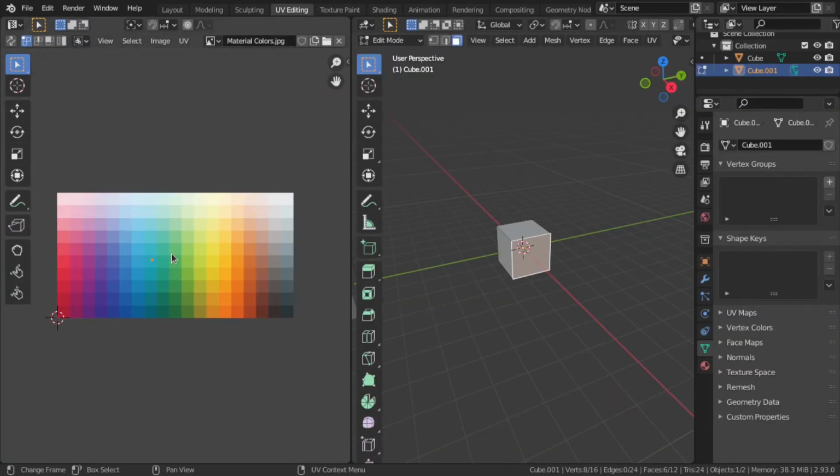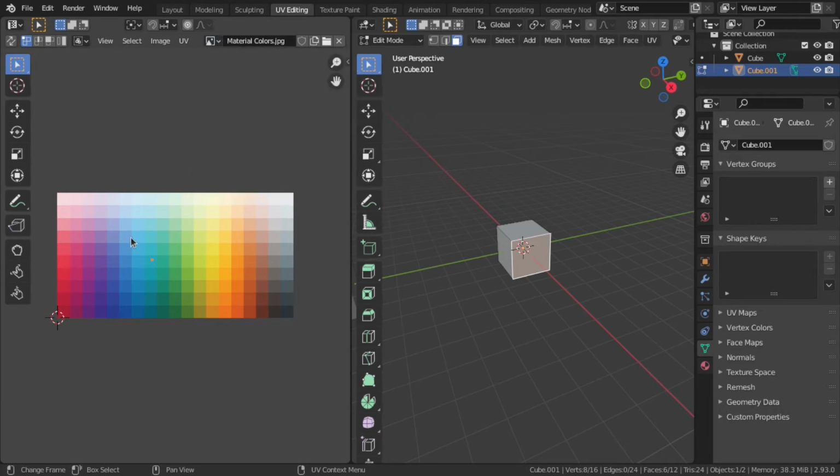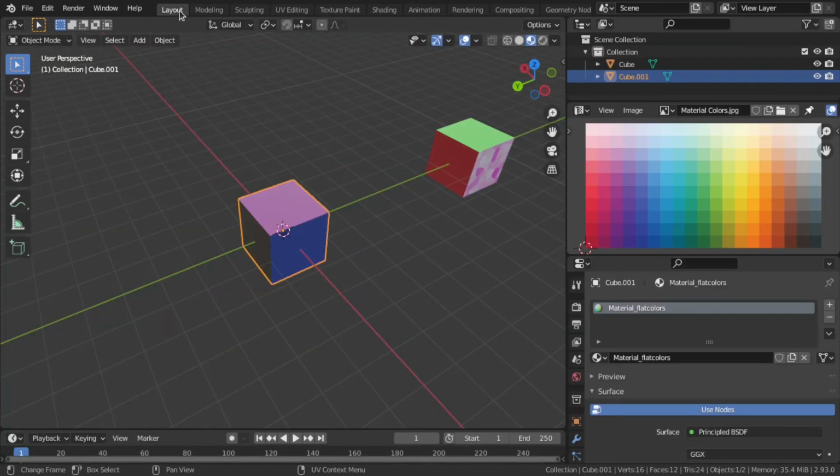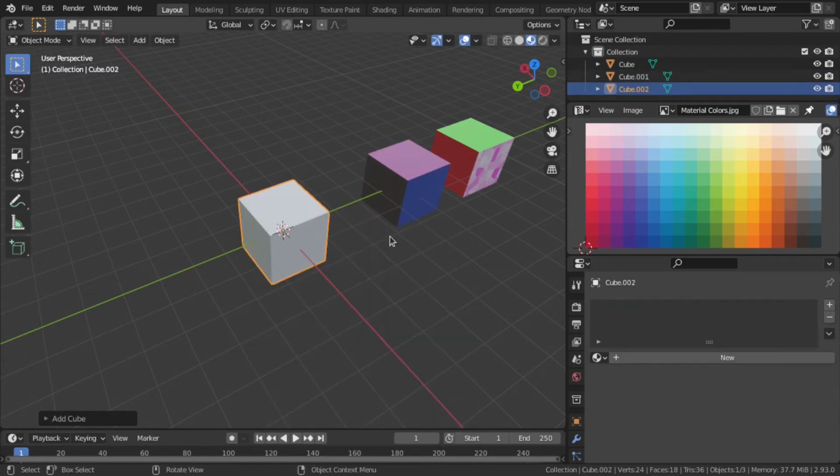Both of these methods have pros and cons. This way you can't customize each color with the other options such as roughness, glossiness, metallicness or emission. You can overcome these problems by keeping a minimal number of materials with different settings but plugging the same color palette to the color input. Anyway, leave that for advanced users. This video is for absolute beginners.